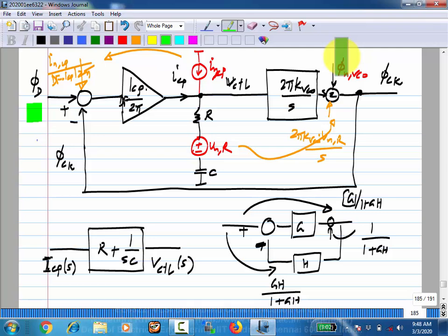So you send something. This is the kind of thing that you would use in, let's say, noise cancelling headphones and so on, right? There is some noise coming in, and then you have to sense and measure how much it is, and then cancel that. So that feedback loop takes some time. So this cancellation will always be effective only up to a certain frequency and no more, because beyond that you cannot follow that noise and then cancel that.